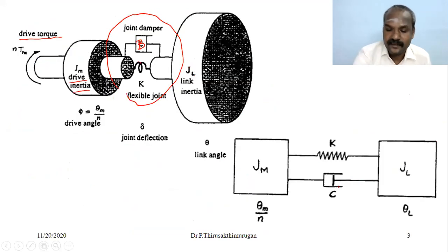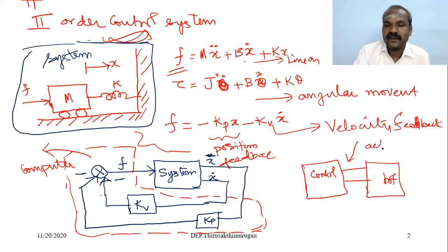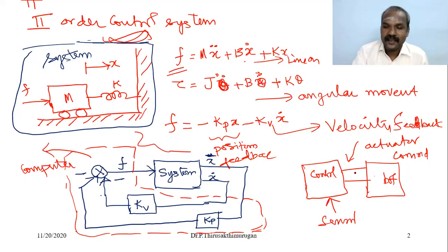There is an interface between the computer controller and the output actuator commands, and the input sensor information. So input to the computer is sensor information, and output from the controller is the actuator command. That command passes to the robot arm, to move in which direction, with which displacement, which velocity, and so on.